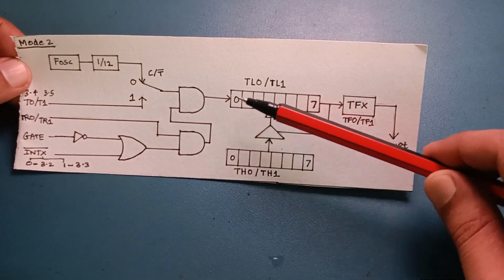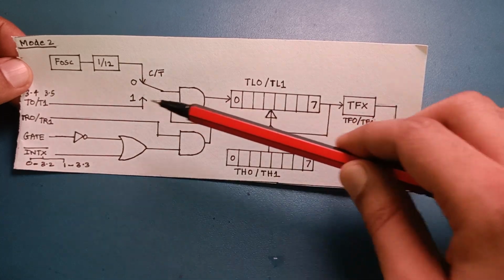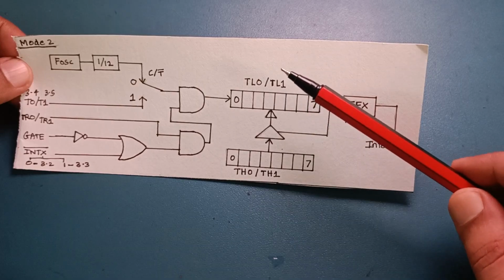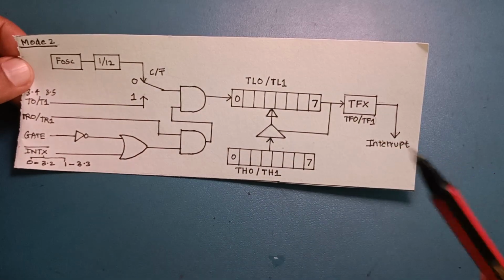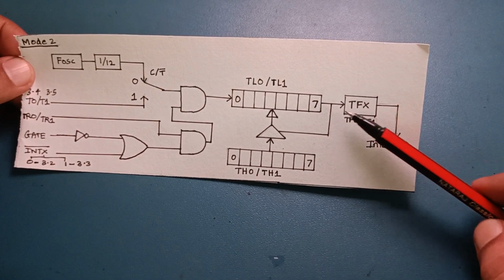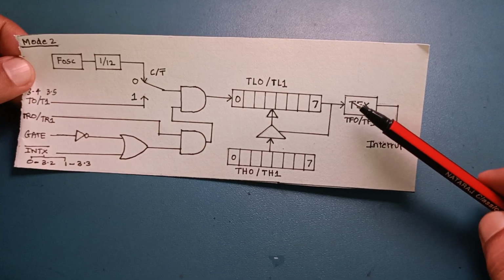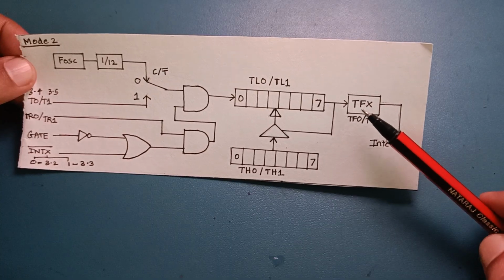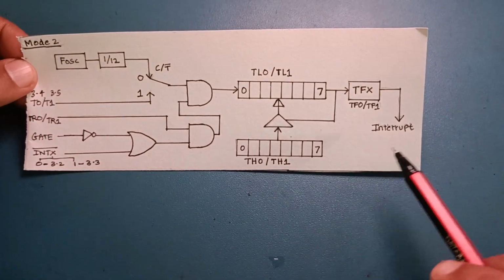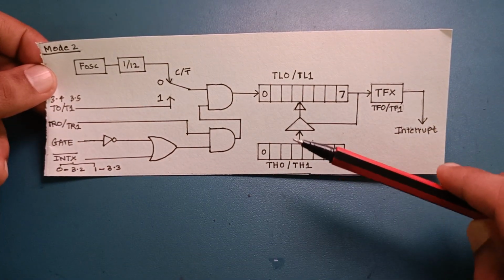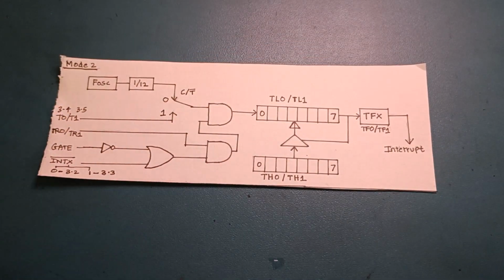Now it will start counting from that value. Suppose it was 3, it will start counting from the next clock pulse. It will become 4, 5, 6, and go all the way to 255, which is FF. And then when it rolls over from 255 to 0, it will set this flag. But if it is already set previously, it will not set this flag again, it will just load the contents again. So this flag needs to be cleared by the software, or we have to call the interrupt to clear the flag. So let's see how the flag is set and the value is loaded from TH0 to TL0 in the Keil IDE. Let's program this and see how this works.